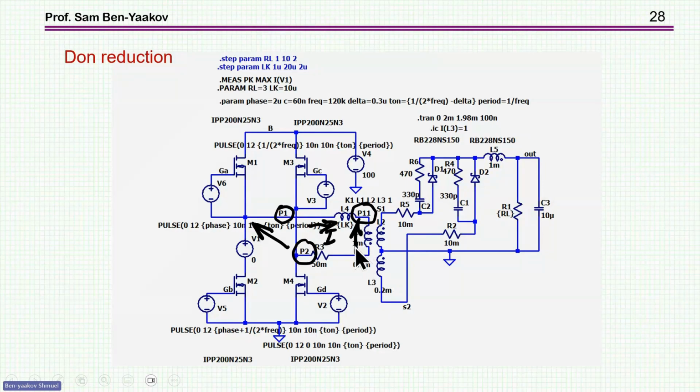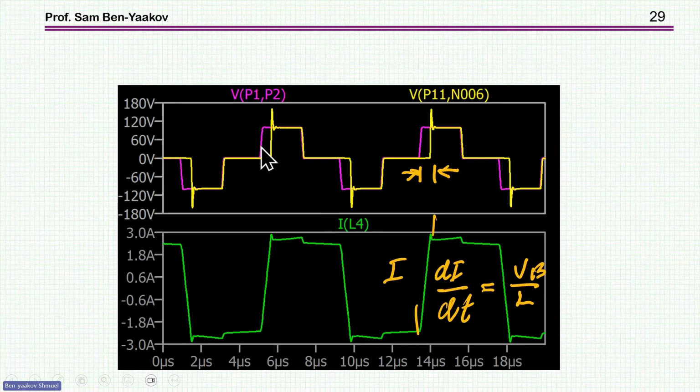Now, this voltage is the actual voltage and the actual duty cycle that operates this rectifier, not here. The voltage at the input and the voltage here are not the same because there is a voltage drop across this inductor. So here it is. The border one is the input to the transformer, and this is the active or useful duty cycle that you have. And this difference is a function of the inductor.